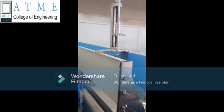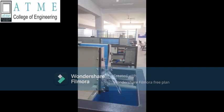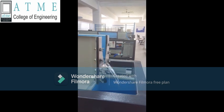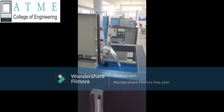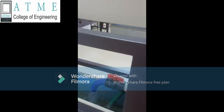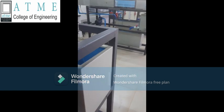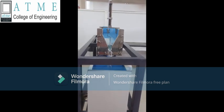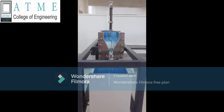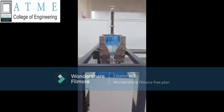So note down the reading H3, and again we have to note down the time taken to collect water in a water tank for a 0.1 meter rise by closing the discharge valve completely. So after the 3 trials, the observations and calculations have to be done, and you have to calculate the theoretical discharge as well as the actual discharge. With that, we can calculate the coefficient of discharge.